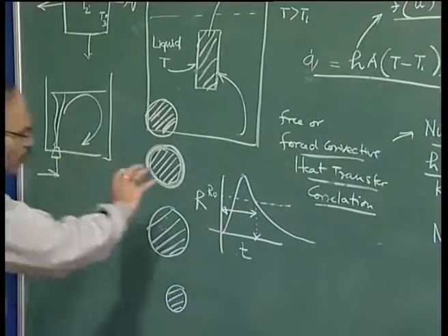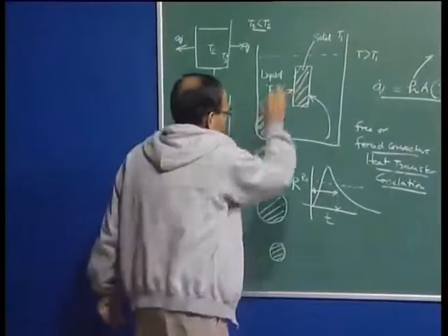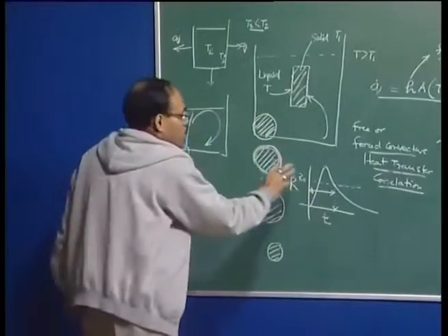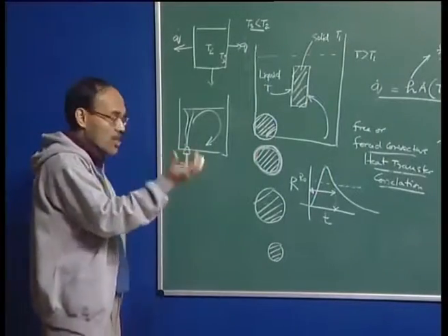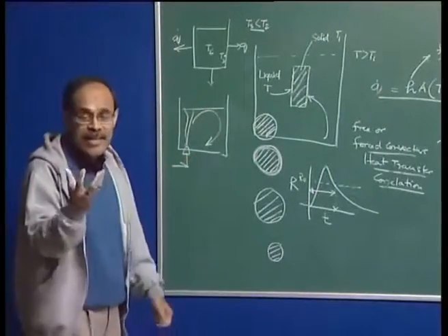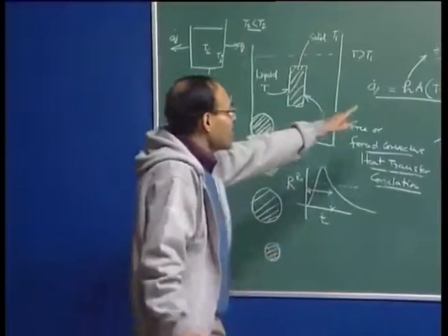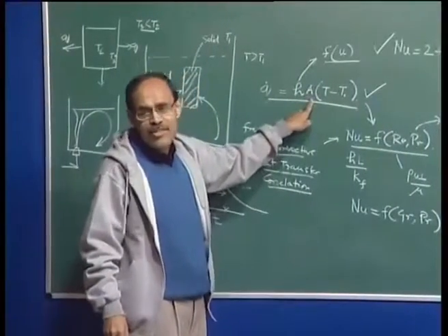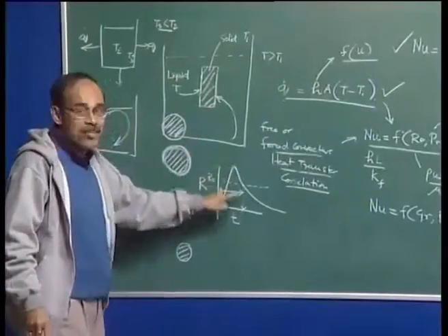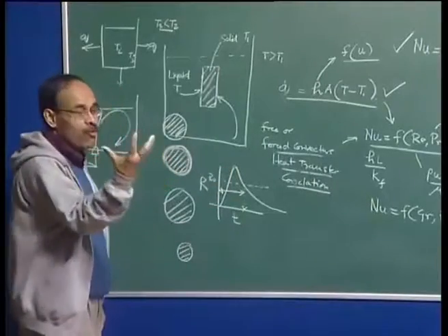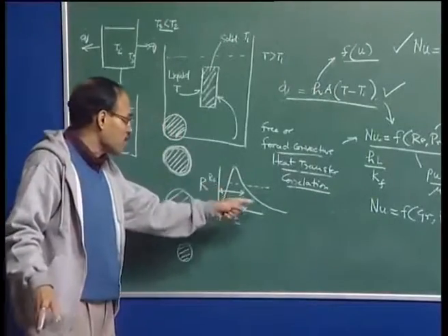Now, in order to calculate this, we have to take into account the latent heat of solidification as well as the latent heat of melting, one is positive, another is negative, and we must also understand that the geometry of the object is not constant all the time. So, this area that I have used in the rate expression will not remain constant during the melting scenario. This is going to continuously change as I have indicated. If you take 4 pi r square, which represents the surface area of a sphere, it is understood that 4 pi r square is going to continuously change during the process.